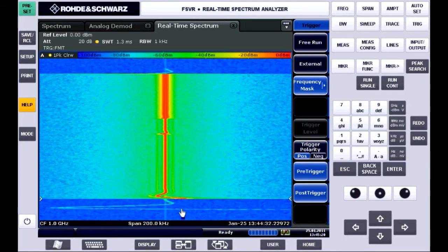Before the burst turned on, before the power amp in that walkie-talkie turned on, we can see that the VCO was settling. It swung from way high over here to about 90 kilohertz low, settled down almost dead on frequency, and then when the power amp kicked on, it settled some more. And then when the walkie-talkie is keyed off, you can see the power goes down obviously, but then there's more settling or wiggling by this VCO. It's kind of interesting behavior.